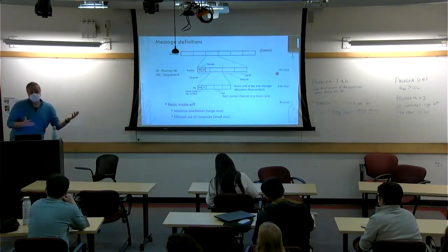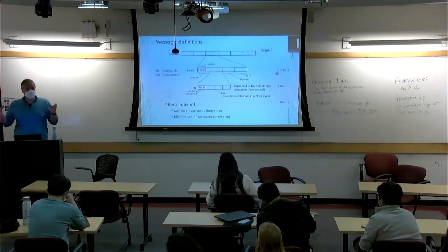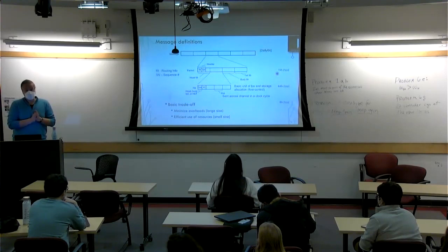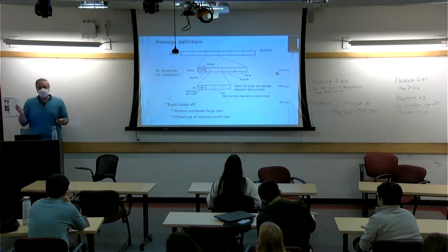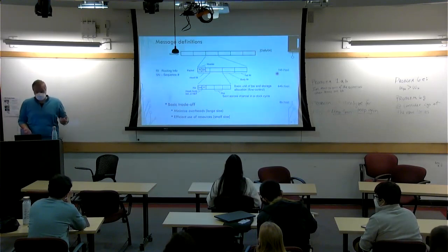And I don't want that necessarily, because you'll see later why shorter packets or flits are also more beneficial. So I'll have some benefits, but I'll also lose on my throughput, right? Because I'm just going to be sending many more headers compared to the bodies that I want to send. So there's a trade-off between, let's say, latency and throughput in this system, right?